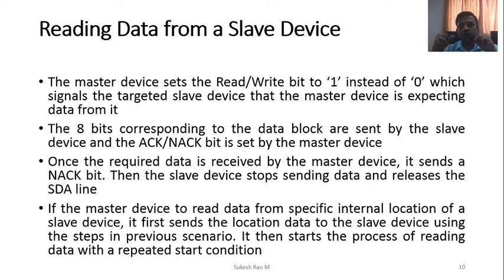Now, in the whole scenario, usually when we connect a temperature sensor, a thermistor should be connected, and from the thermistor I need to get the analog value that has to be converted to digital by A to D conversion. All sorts of things need to be done. So the recent trend is not that. What we do is we use a sensor which has an I2C bus. It's a system on chip which takes care of all the conversion, and you get ready digital format data. So it is the latest trend.